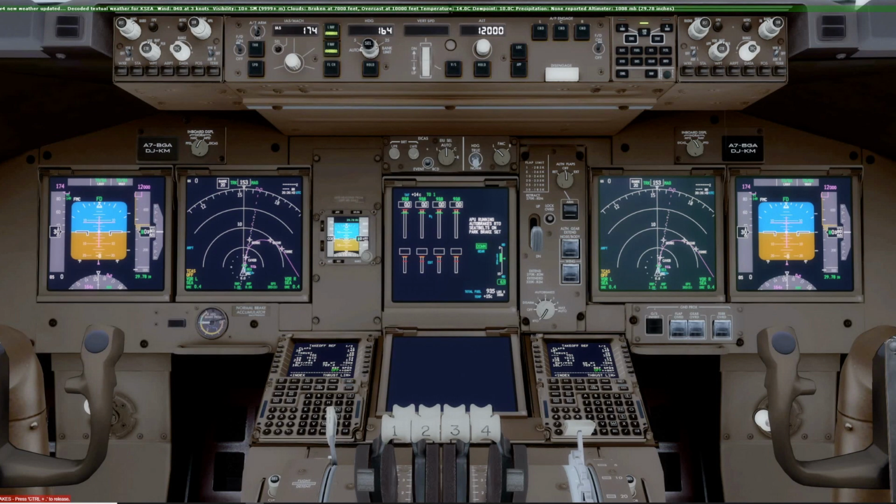And then he'll say, okay, your nose gear steering is locked out, and release your parking brake. And then we'll go ahead and release our parking brake and begin push. And then we tell him any specific instructions like tail north or tail in the alley or whatever.